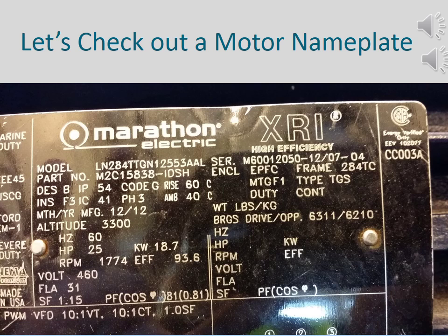For example, if we have a pump that is spinning at 1,700 revolutions per minute, or RPM, and we speed it up to 1,800 revolutions per minute, what are we doing? We are increasing the flow and changing the load or horsepower requirements on that motor. We need to understand that we cannot ignore the revolutions per minute when we change out a motor. We have to try to be close, because this has already been thought about in the design. With the pump, we need to be careful about changing speed, because flow and horsepower are related to speed.